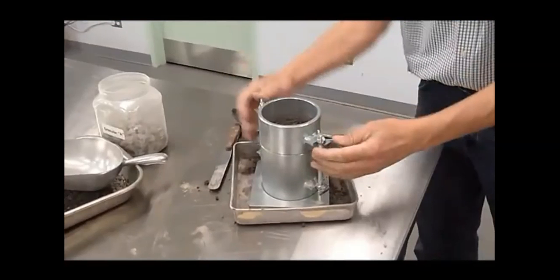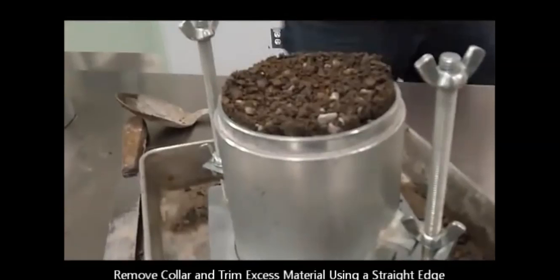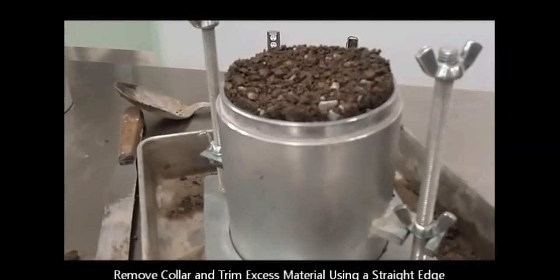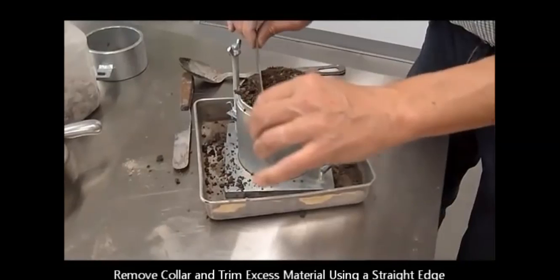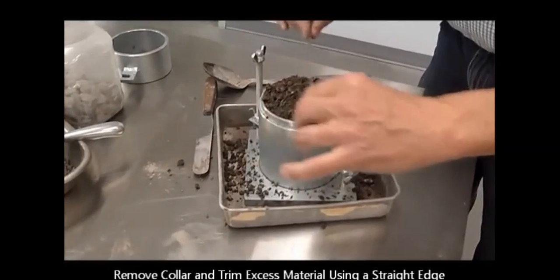So I'll detach the collar. Now we can see it is slightly more than the top level of the mold. So I'll trim it off. I'll trim the extra soil exactly to the top of the mold.